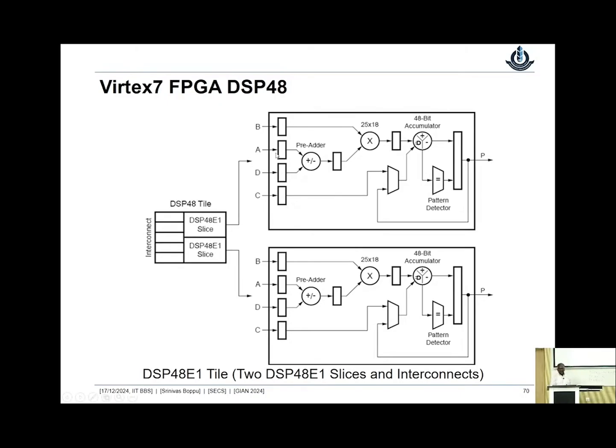do it. And now if you look at here, we can also add or subtract them. So I can do a plus or minus d multiplied by b, yes or no? This is a dedicated block, hardwired, which is instantiated. Similarly, I can also do some kind of bitwise comparisons and all. So whenever, as I said, additions and dedicated multipliers are used, this DSP tile is going to be used, right? And again, as I said, if you have more of these DSP slices, that FPGA is going to be a bit expensive.